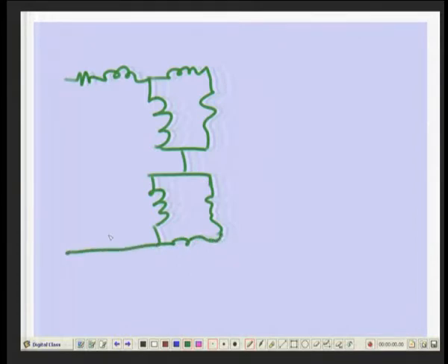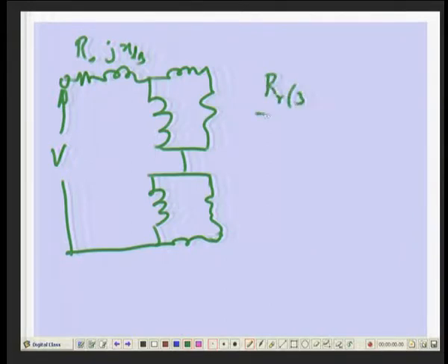This is the equivalent circuit we get. RS, JXLS. Okay. Now, only thing is in one case you get XM by 2, another case is XM by 3. You have RR by 2, RR by 3. So, the only thing is, see, RR in 3 phase divided by 3 is equal to RR in 2 phase divided by 2. So, you need the rotor resistance in both models are not same, because you must recall what is known as 3 phase to 2 phase transformation.